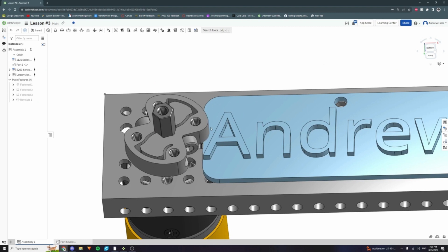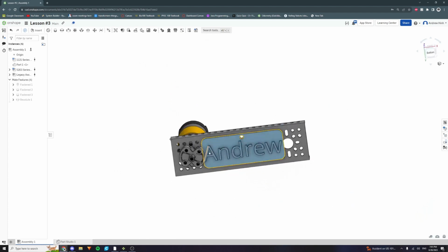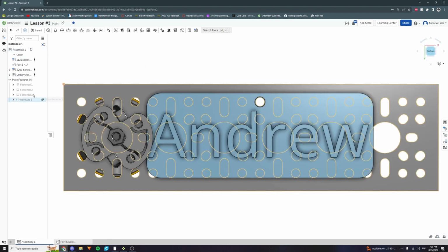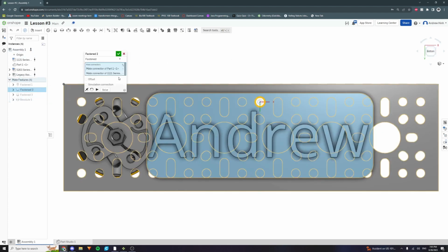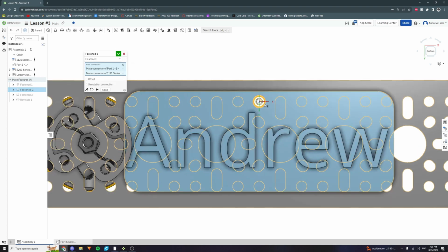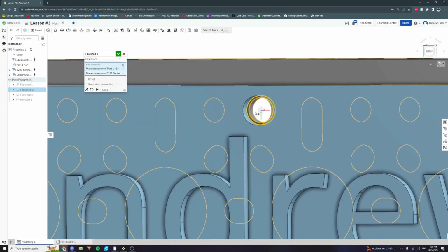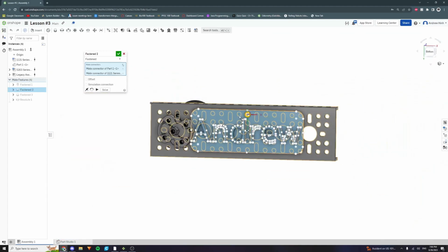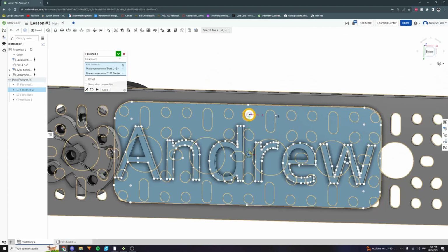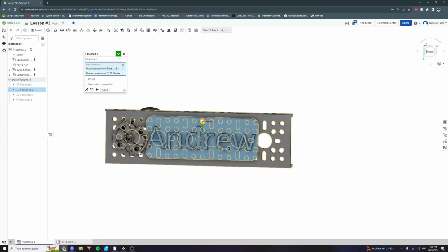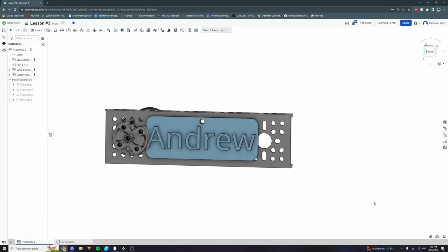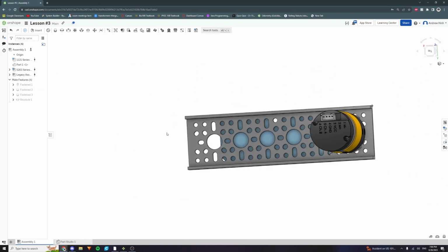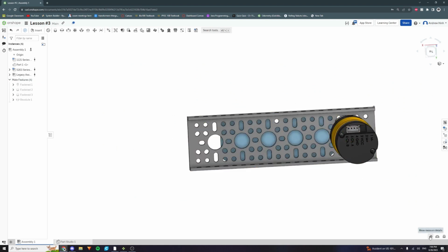Now there's also things called mate offsets, which you can always edit whenever you fasten it. So let's say we want this part right here to be a couple more holes down, like right here, for instance, so that this sonic hub doesn't get in the way. What we can do is, whenever you offset, you want to know the distance.